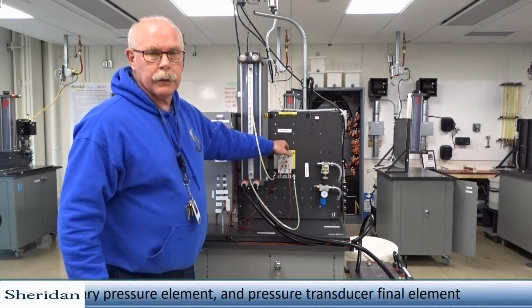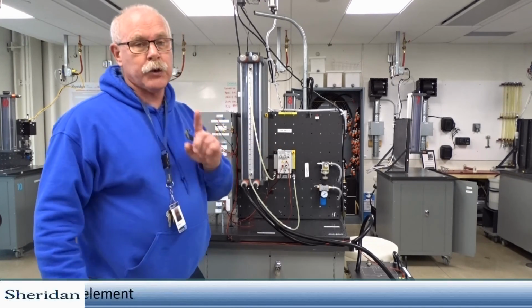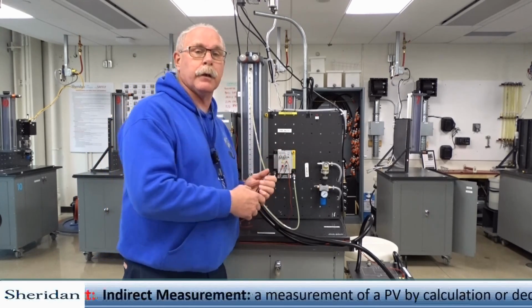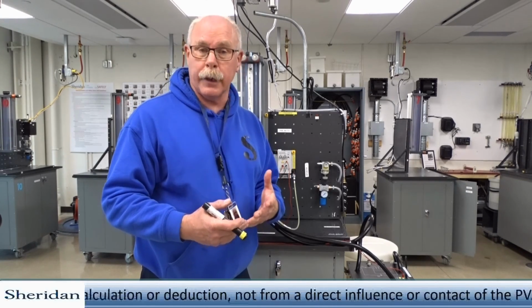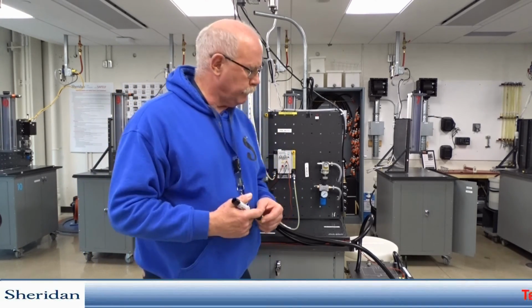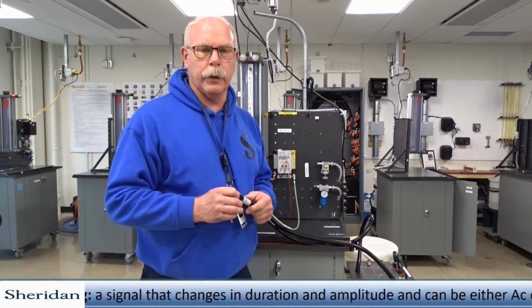We measure the level in the tank by this pressure transmitter. Now the pressure transmitter measures the pressure at the bottom of the tank. It is not directly measuring the level of the water, so this is an indirect level measurement. This transmitter translates what the pressure measurement is at the bottom and gives an output to our control which is directly proportional to the level. It's an analog signal, 4 to 20 milliamp signal.